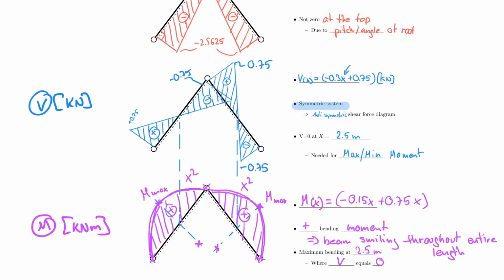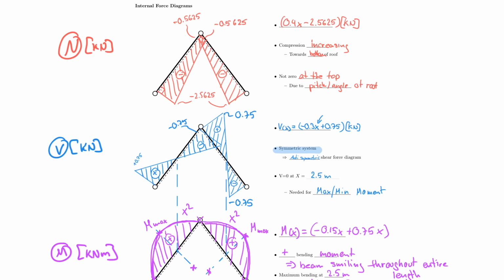And so you see now that we actually completed all 3 diagrams for a non-rectangular frame with self-weight on it. And once again, the logic is no different. What was challenging here for this problem was to first find the support reactions. And after we find the support reactions, we had to break them down into parallel component and perpendicular component. And then we created these functions, and these functions helped us to really draw the system.